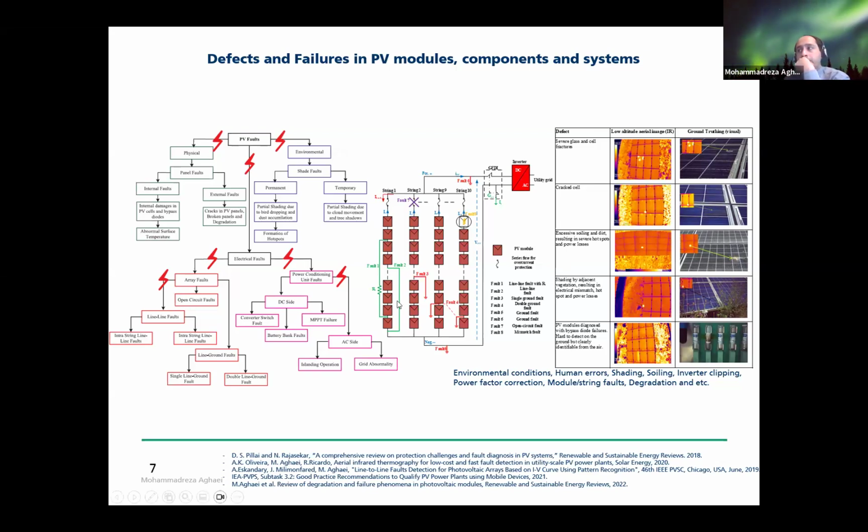And the electrical faults, as you can see in the middle, include DC faults like line-to-line, line-to-ground or mismatching, open circuit faults, and ground faults. However, these faults can also be the consequences of some other faults that may appear on the PV panels. And it's important that you consider this and do the monitoring for both sides, the electrical side and also the RGB or thermography analysis.